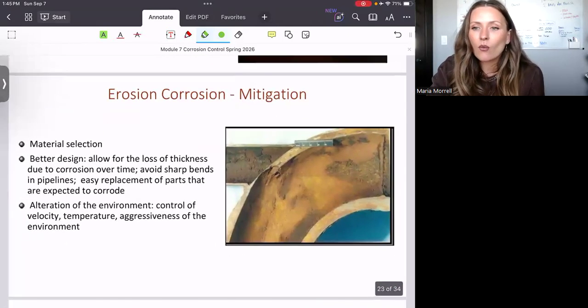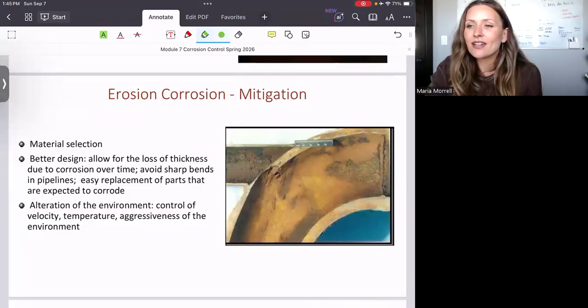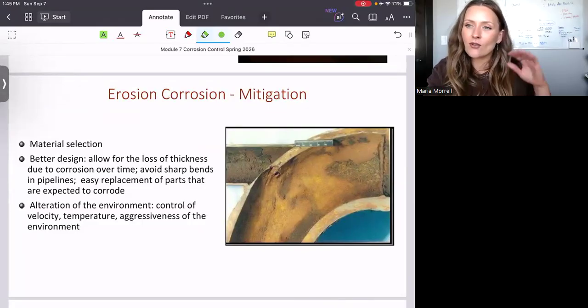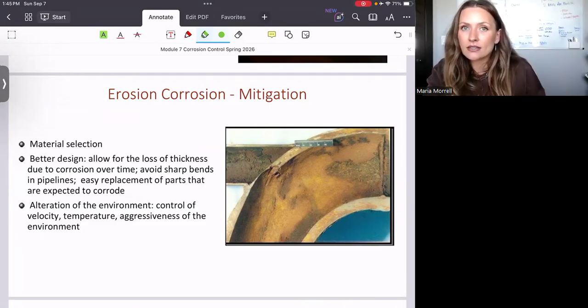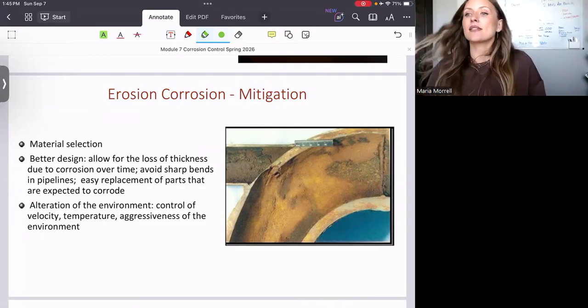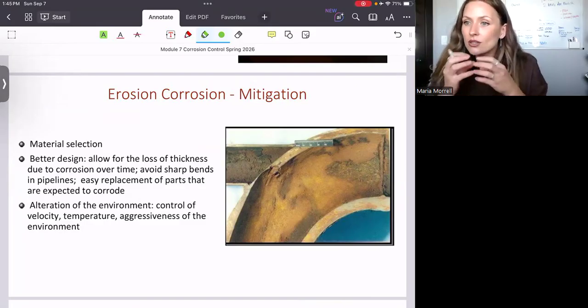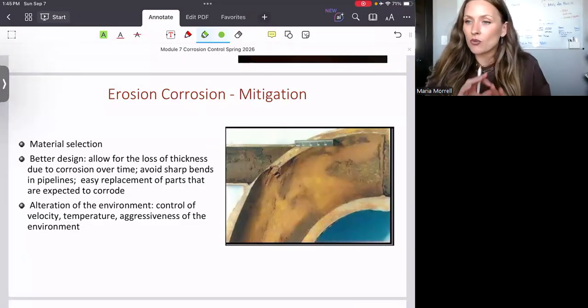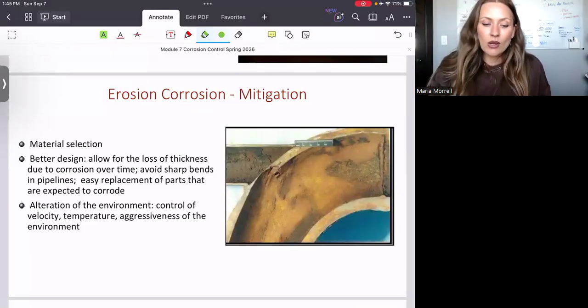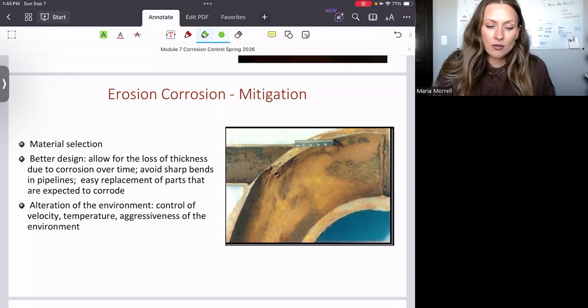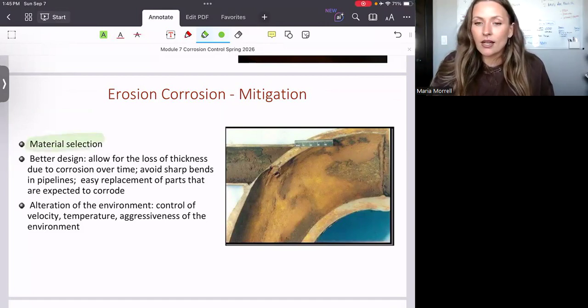Erosion, without definition, I hope that people remember, erosion happens due to the abrasive motion of the fluid, right? And I'll tell it again, the fluid doesn't have to be a liquid. It could be sand, it could be slurry, it could be paste, it could be particulates moving, right? Doesn't matter. By fluid, there could be a lot of things, but the way we mitigate it, well, first, of course, it's going to be material selection, right?